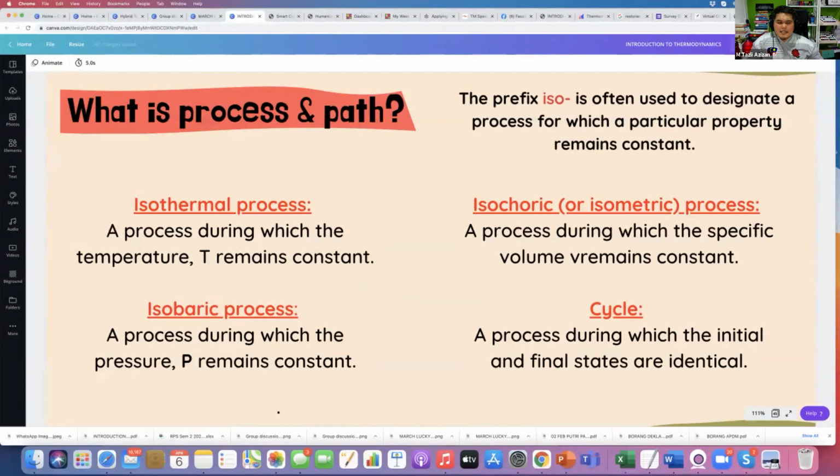Okay, Izzati said it is an isochoric process because there is no change of volume. Because we close it properly, there is no change of volume. There is a change of temperature. Temperature definitely changes because we heat up the kettle. There is, of course, a change of pressure because when we close the system, the gas inside the kettle is trying to get out, so it hits the wall of the kettle. So it is definitely not an isobaric process. So it is an isochoric process.